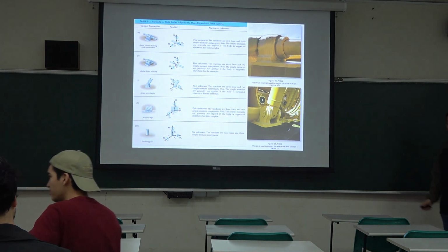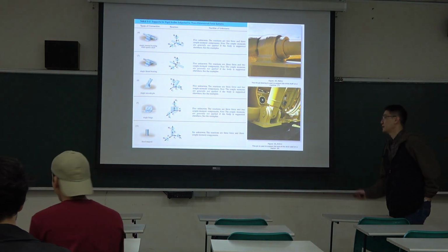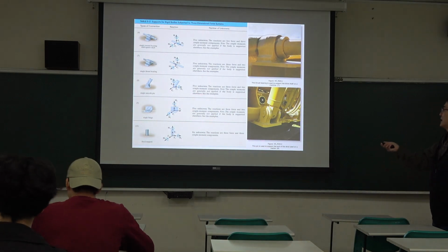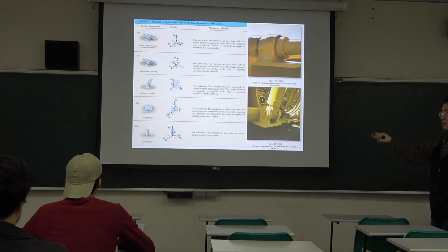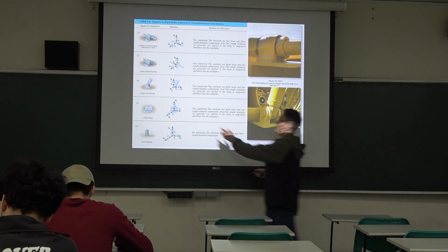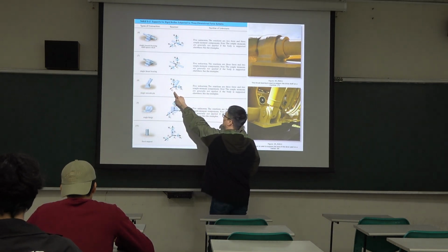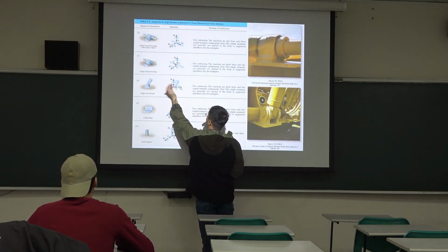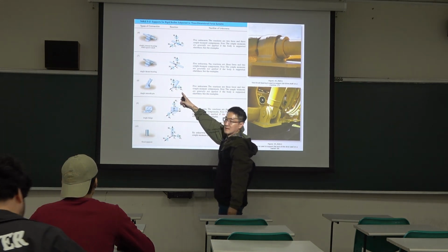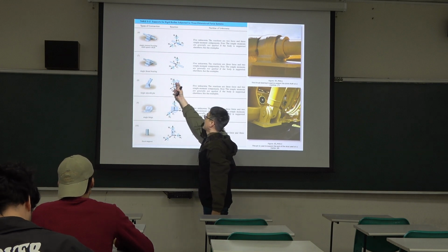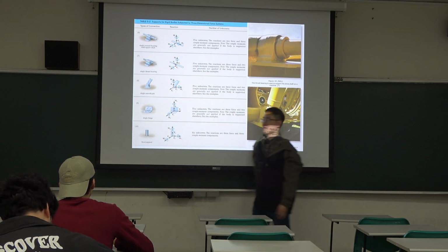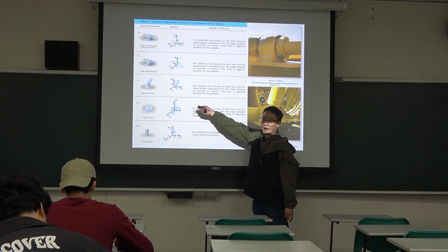Okay, so yesterday we finished here. Here is a single smooth tip. We finished here, so it allows rotation this way. Therefore, it cannot provide a rotation resistance for the x-axis, but it can prevent rotation for the y and z axes, and also it's a pin connection, so it can have 3 directions of reaction.